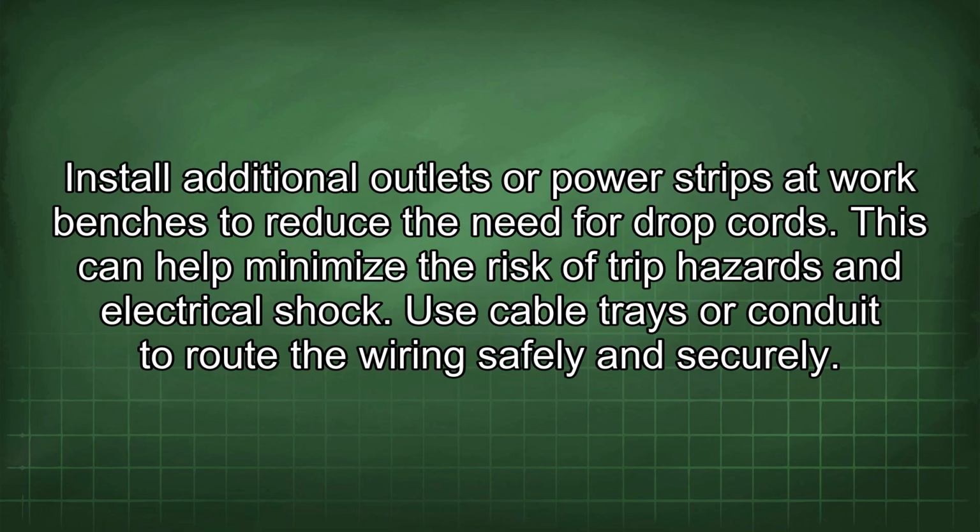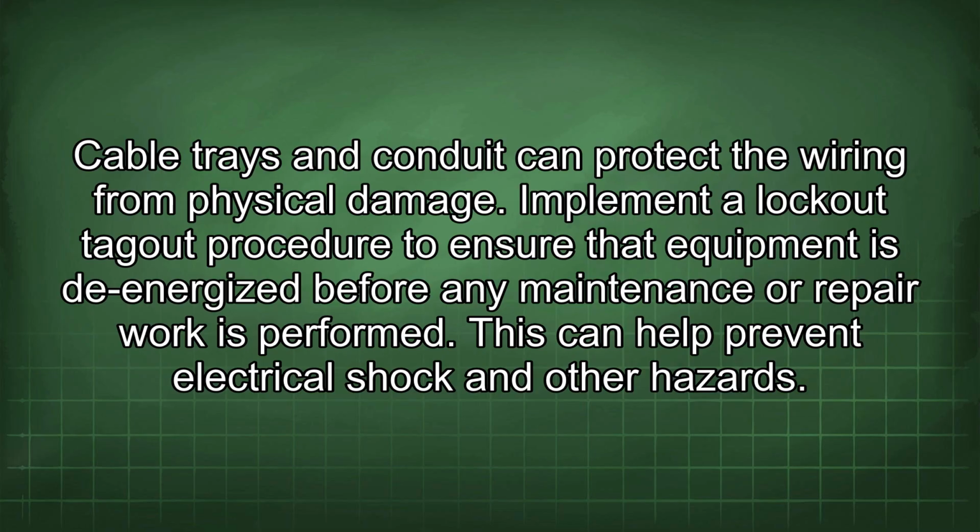Install additional outlets or power strips at workbenches to reduce the need for drop cords. This can help minimize the risk of trip hazards and electrical shock. Use cable trays or conduit to route the wiring safely and securely. Cable trays and conduit can protect the wiring from physical damage.